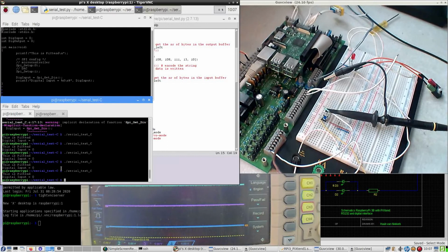So I most likely should change the setting schematics. Or I have to increase the voltage. How much voltage does it need to operate? I have seen the LED burn weakly, but if you want to have it burn brightly, you have to increase the voltage. So I think 2.5 volts is even too small to have it burn really. Interesting thought. So how do I accomplish that? Probably by taking away the resistor.